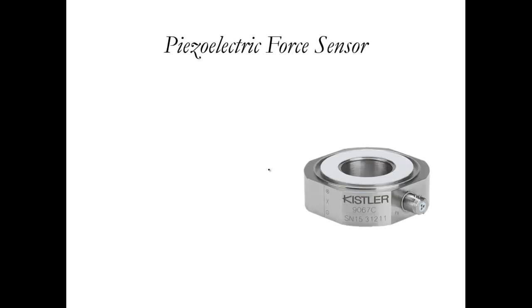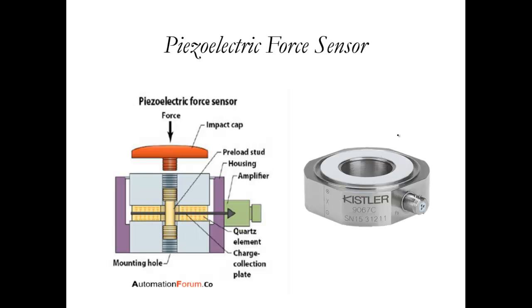We also have piezoelectric force sensors. They look similar to this in the industries, and the principle is almost similar. So you have a force that is being applied on the impact cap. You have a preloaded strut or the stud, and then you have housing, you have an amplifier, you have a quartz element, that is the piezoelectric element here, or the crystal is here, and then there is something called a charge collection plate mounting hole. So the moment you apply a force, this compresses the piezoelectric material, and accordingly charge is developed, and that is amplified and then fed to the controller.